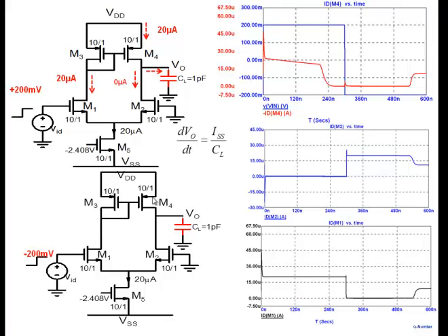See here. You have to go back and think of why we said that current switching cannot occur. We said M2 was in the linear region. But remember, this is 3.3 initially. Until the capacitor discharges, this cannot go into the linear region. So when it starts with 3.3 here, this is in the saturation region. So then what happens? Actually, current switching occurs here.